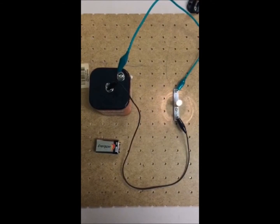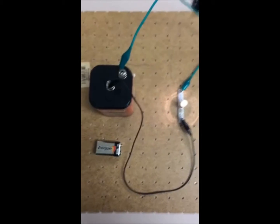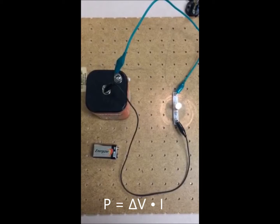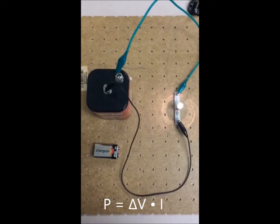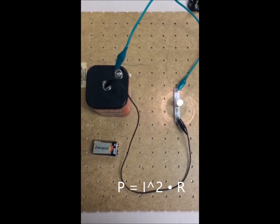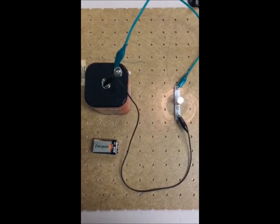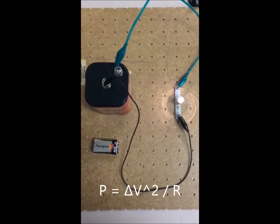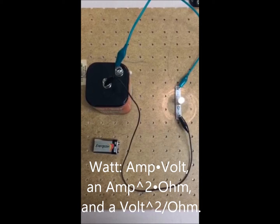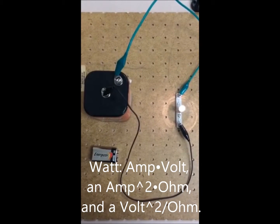Since the charge over time ratio found in the above equation is equivalent to the current, the above equation can also be written as power equals the change of V times I. By combining the Ohm's law equation with the above equation, two other power equations can be generated. They are P equals I squared times R, or P equals the change of V squared over R. The standard metric unit of power is a watt. In terms of units, the watt is equivalent to an amp times volt, an amp squared times ohm, and a volt squared over ohm.